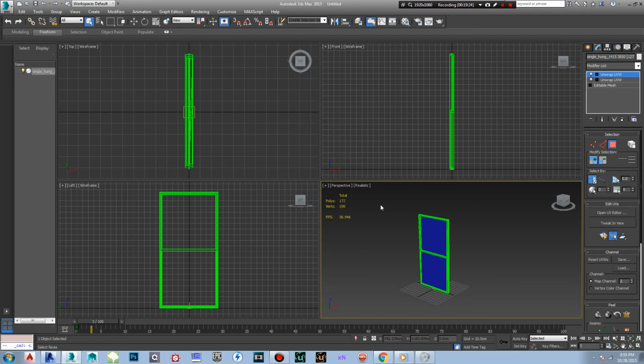Now, like I said, usually, again, let's say you made a model in 3ds Max at your friend's house or at school, and you had different customized settings for a different project, and you made the model and said, oh God, I forgot I did that. You just spent an hour and a half building it. Don't worry about it. Just save it as FBX, okay? Make sure when you do that, under the settings, under units of the FBX files, a lot of people will just go over this and press OK. Make sure automatic is clicked and centimeters is selected underneath it. Then you'll be all set. When you import it into 3ds Max at home, you'll have no problem.